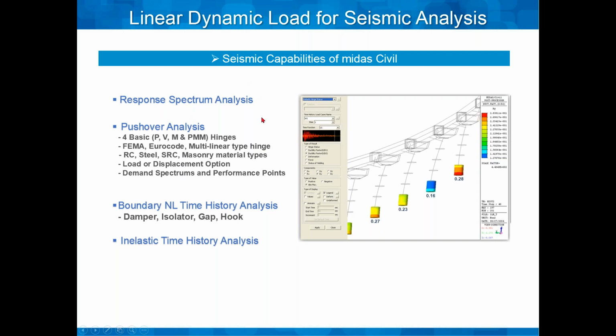Pushover is our non-linear static analysis. Then for dampers and isolators, we have non-linear time history analysis where seismicity is taken into consideration. And you can also specify non-linear hinges and perform a dynamic analysis. So non-linear dynamic analysis is also possible in the program.